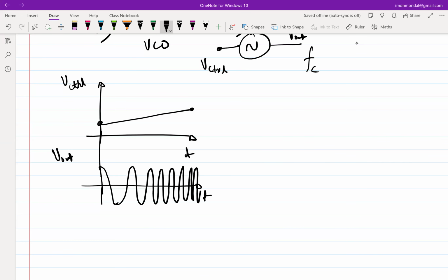So you have something now, you fabricated something. Maybe after 5 minutes, it will probably change to some value which is maybe 1 ppm away from whatever you designed. After another 5 minutes, it will probably change to something else, and keeps on happening, which essentially means that you will not be able to tune your center frequency to exactly what you want. And that is important because if your center frequency shifts, then what happens to the receiver?